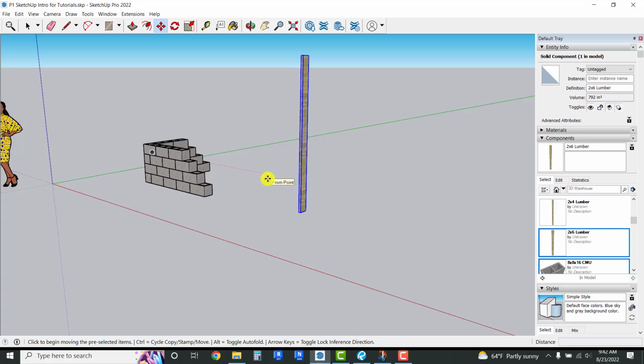So the first thing I'm going to do is use the rotate command to lay the lumber down. I'm going to select the rotate command from the toolbar. Now this time we're going to actually rotate around the red axis. It means that if this right here was the direction that we were rotating, then we'll be actually going around this particular axis. So remember those really nice lock keys, and right is for red. So first I'm going to lock my axis to red and then select my pivot point, and I'm going to choose either of the bottom corners is fine.